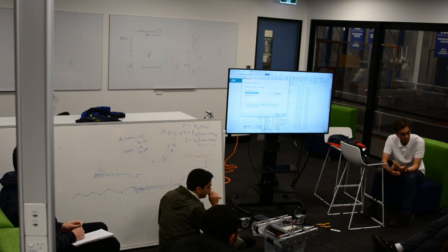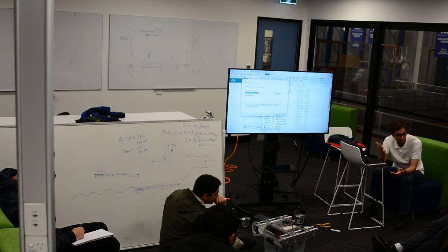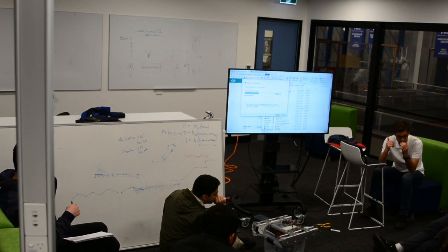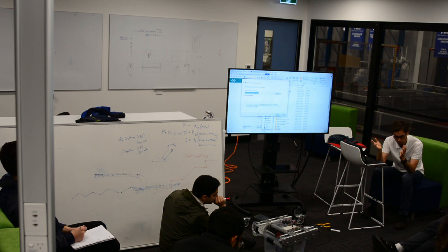Well, remember that's not deceleration. What that's putting out is the voltage you apply to the motor, and that's not equal to speed, right? By the time you get to steady state, it is equal to speed. If you double the voltage, your steady state speed should double. But the dynamics of how you get to a speed are governed by the torque speed curve of the motor, which is sort of linear, but it's got all this friction in it as well.